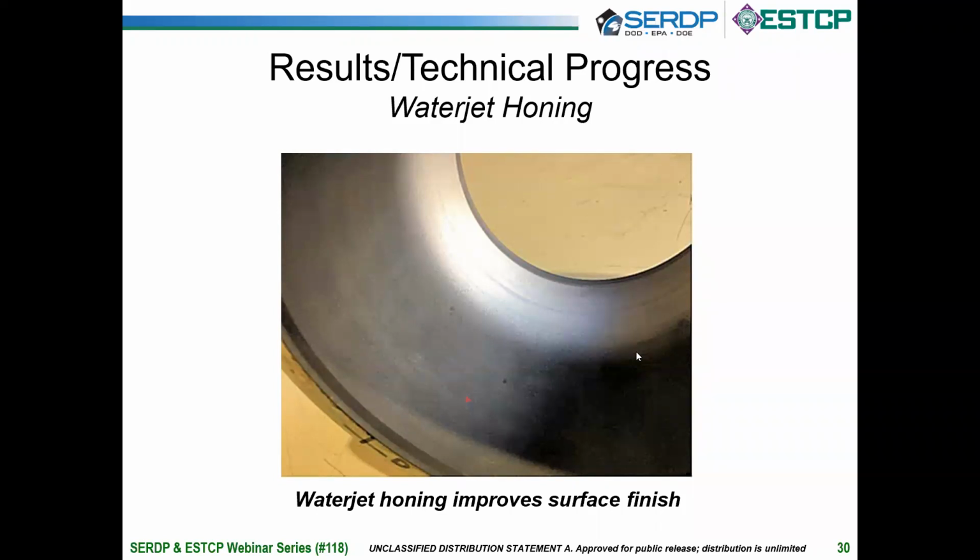Again, this prevents the barrels from having to be reversed or replated, or using any solvents or chlorinated paraffin lubricants where you're using machining processes to strip the coating, which is traditionally done. The waterjet process is an environmentally clean process, and it just really makes sense to use.